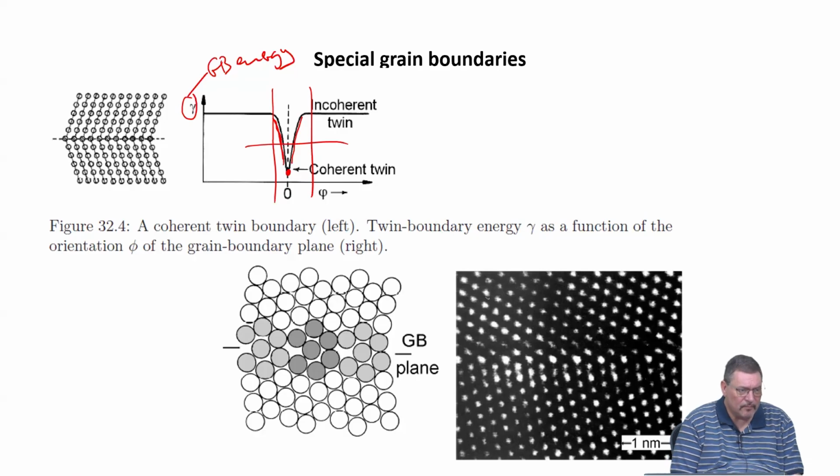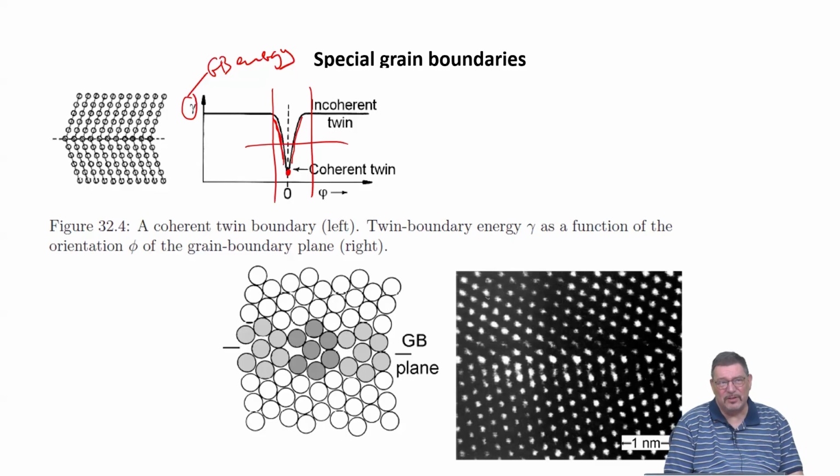So from the tip of the twin, we can identify if it's like a deformation twin or like. This is very difficult. Yeah, you can look at it in terms of shape, yes. If it is very straight over a long distance, and you do not see many dislocations associated with it, like strain fields, I mean, you can look at the kernel misorientation maps associated with the boundaries, and if this is rather a uniform color, that means that there is no strain variation along the boundary, and then it is a good indication that this might be a grown-in twin. For a deformation-induced twin, you would think more variations, or you get maybe steps in it or something like that.